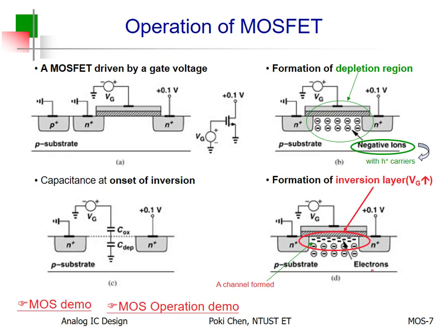And then, this is the most important slide till now. How to make such a MOSFET functional? Because from the very beginning, it is off. How to turn it on? How to make your MOSFET conduct something between the source and drain instead of nothing? From the very beginning, you need to take away the parasitic diodes. Let me see. Yeah, see? That is what I can help. From the very beginning, you have 2 parasitic diodes there.